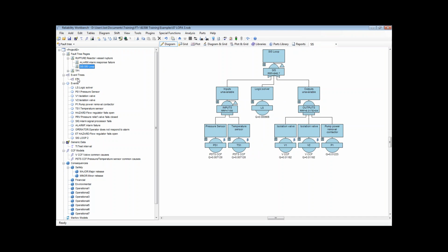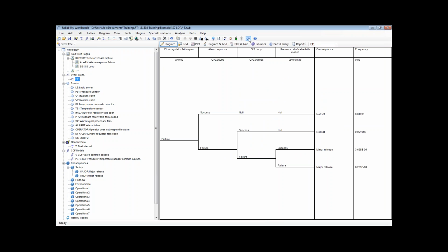That little bit of math that I did, dividing my point risk by my target, tells me how much further risk reduction I need. Maybe I need an extra layer of protection with a risk reduction of 4, or maybe I need to increase one of my current systems' risk reductions by a factor of 4.